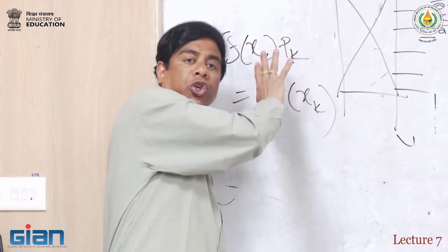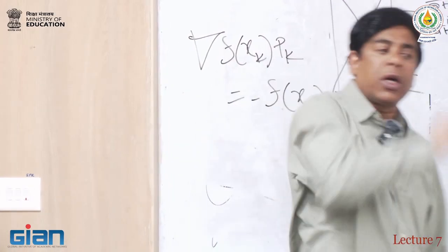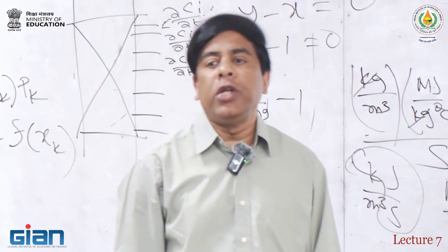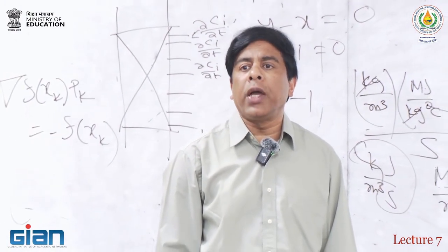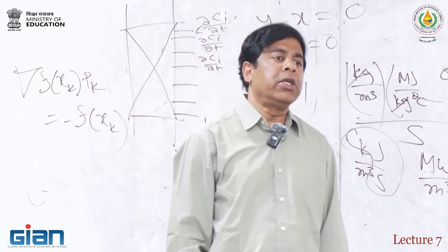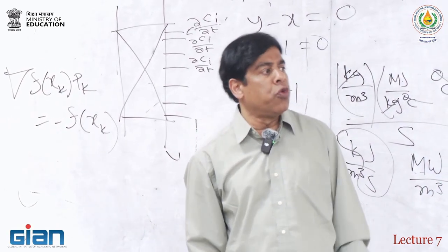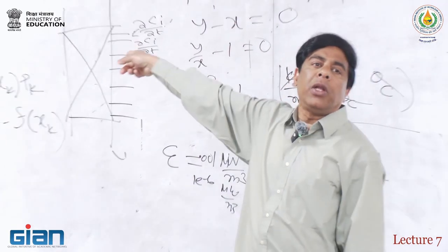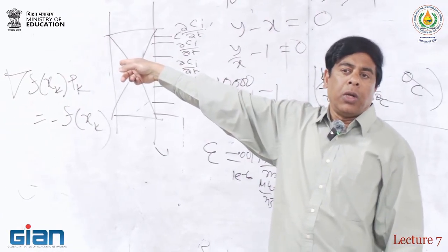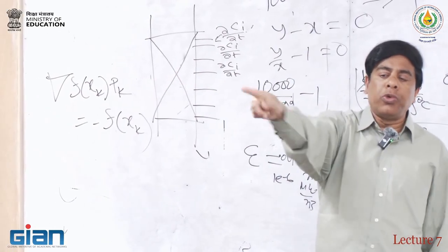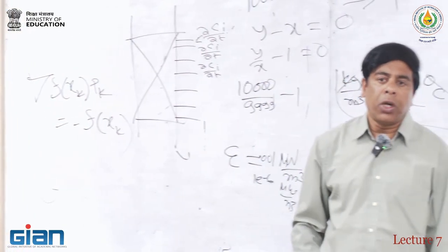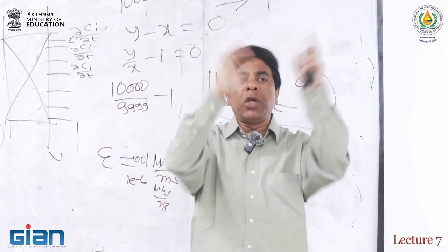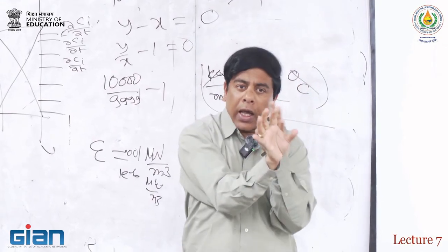So this is a matrix equation, n by n. This is the guy that takes most of the time. The linear equation solver takes most of the time, depending on how gigantic your system is. If you have 10 million by 10 million, this is a 10 million by 10 million matrix. In previous generations, most of these computers would actually run out of memory to do these things. So they do a lot of decompositions behind the scene and ask, can I handle this size?